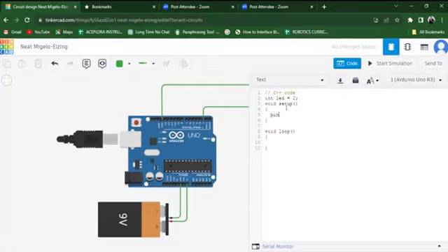So you write pin in lowercase, put a capital M, and put ode. pinMode is one word, but the M in the middle is a capital letter, right? When you've done that, open a normal bracket. In that bracket, the first thing we do is to write either the variable name or the pin number. So you can write LED or 2. Since you've assigned LED to 2, this is just like saying X is equal to 2. Then anywhere in your code you see LED, you can use 2. Anywhere you see 2, you can use LED.